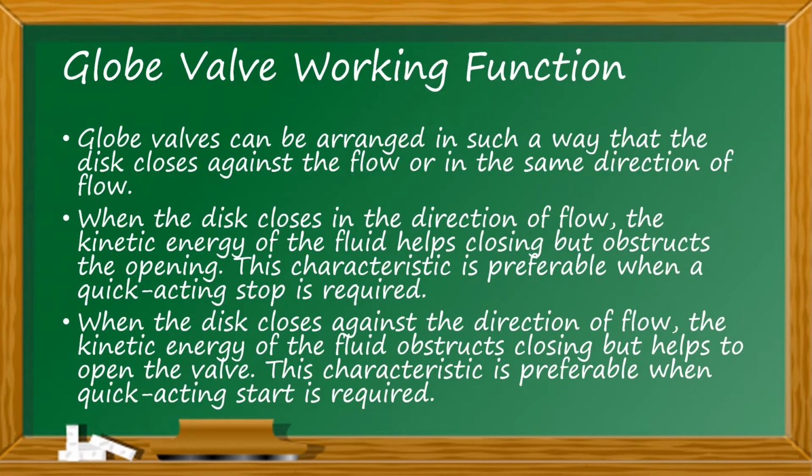Now the globe valve works in a way that the disc closes against the flow, or it is in the same direction as the fluid flow. When the disc is closed in the direction of flow, the kinetic energy of the fluid helps closing but obstructs the opening of the valve, which is preferable for quick acting of the valve.